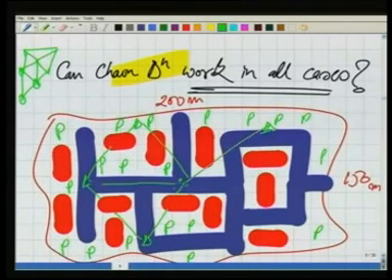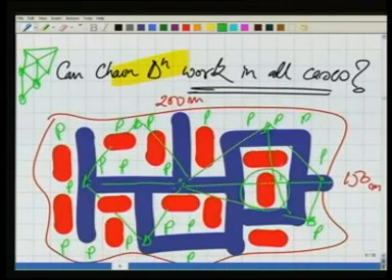Okay, I can go for a line here, maybe another one here, but it's not a triangle. If I want to make it a triangle using this line, I cannot. Neither can I with this, because the lines of sight are obstructed by these buildings. Now I have made a rough drawing here. You can think of your neighborhood, just outside the room where you are watching this video lecture. Think of that area. Triangulation can be done only in those areas which are flat and where visibility is clear. Only in those cases can we do the triangulation, but not for an area like this.